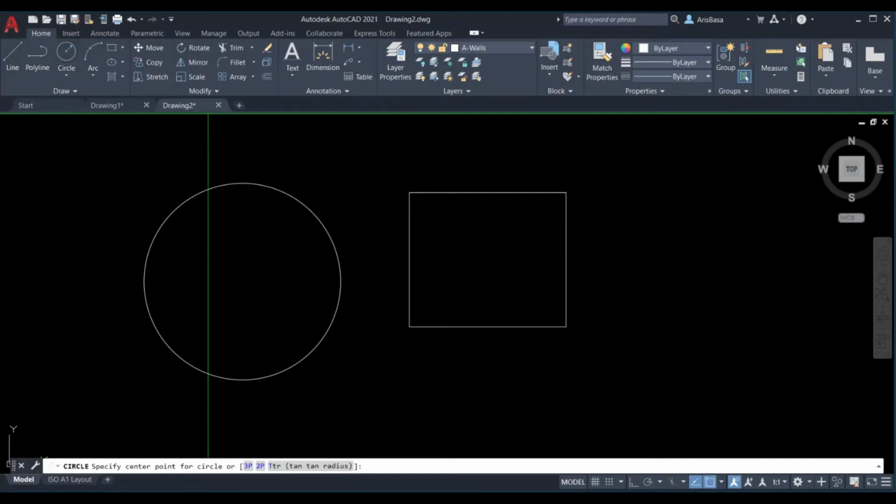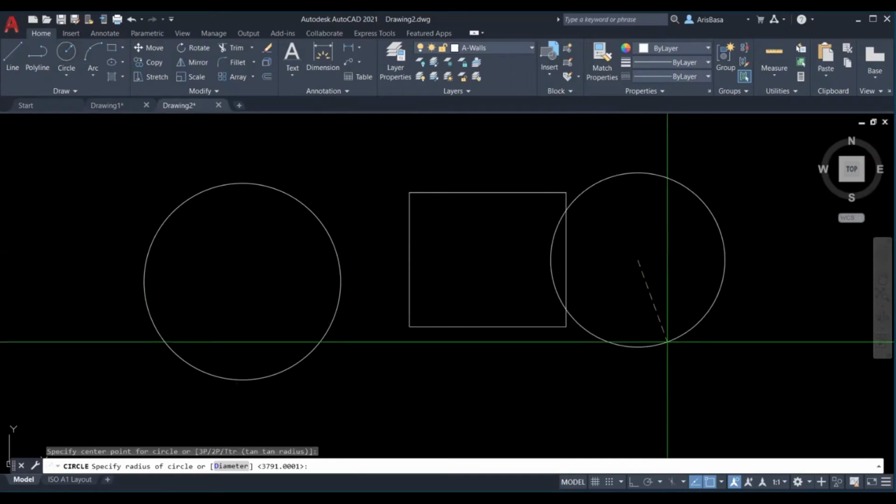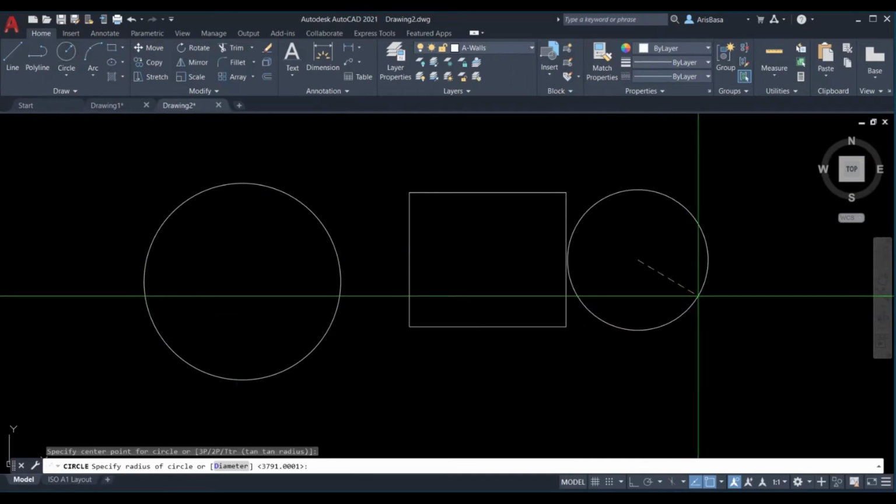Anywhere in the drawing area, you can just click and then you'll create your circle. This is not a completed command yet because it is asking you another question. It says specify radius of circle. So you can either enter a value. By the way, we'll be using millimeters for the duration of the course, since this is what we use.